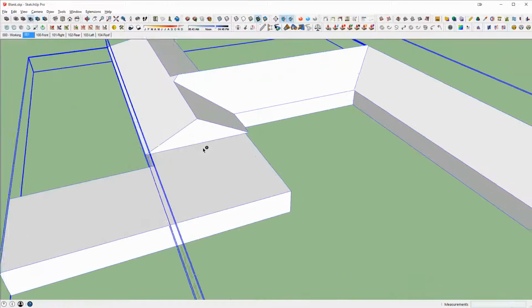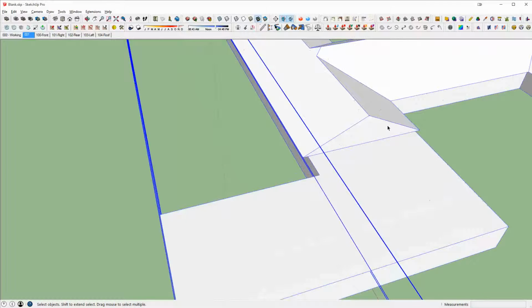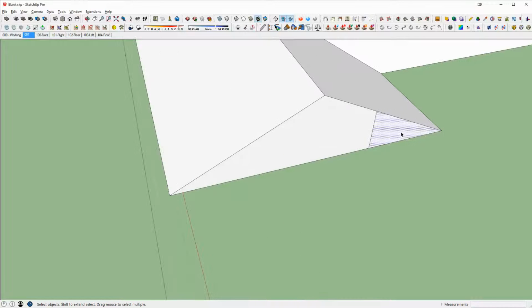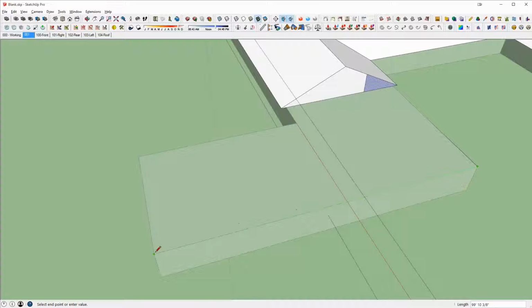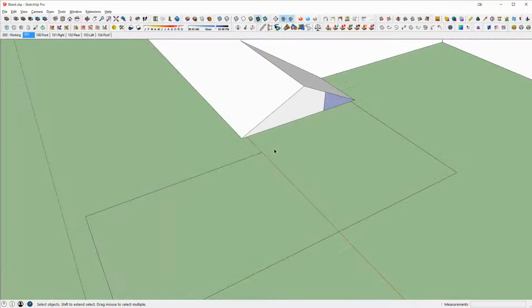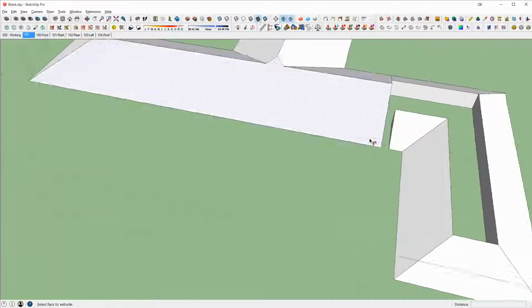And you can see I can quickly get rid of that roof in a place where I can now just quickly rebuild the roof over here. I'm going to draw a vertical line, hit my blue axis, and then down here, and simply going to draw a line around the new part of the house and just come just short of the roof. It just helps to keep things a little cleaner sometimes. And if I select the path I want it to travel, just the pieces I need, and then F for this roof to follow, you can see I quickly added that piece on.